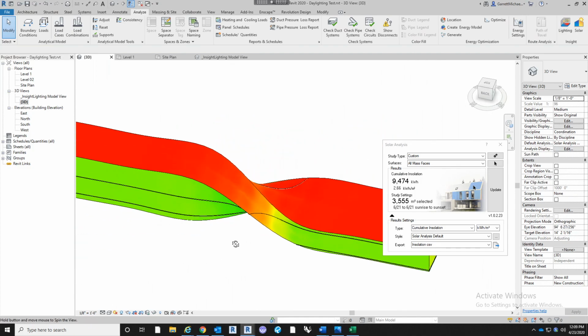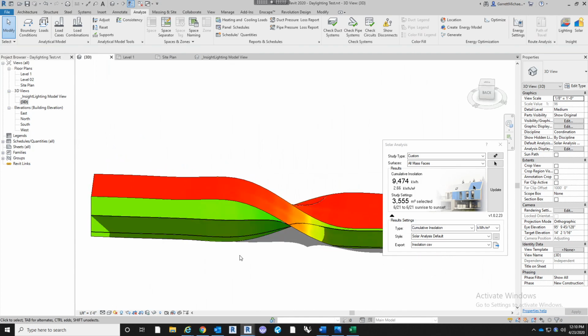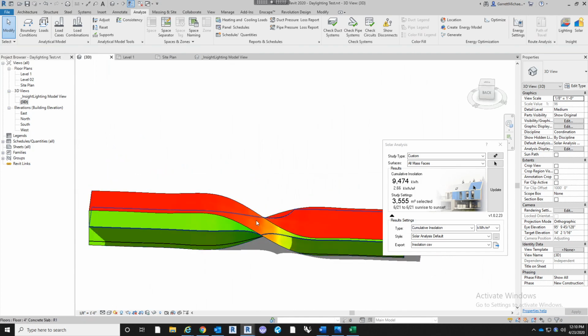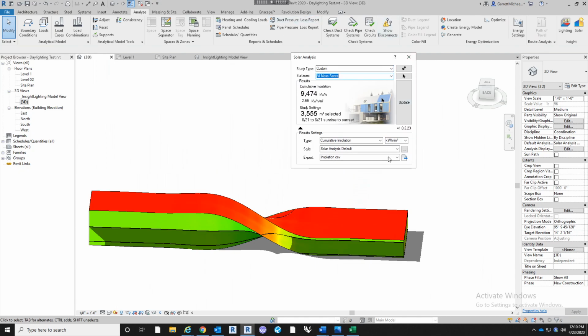And maybe if we wanted to have glazing running up this wall and onto the ceiling, since it does have significant amount of solar exposure on the top roof, and when it twists, maybe we identify some shading devices on that roof to reduce the amount of solar exposure onto the glazing while still getting the benefit of natural daylight.